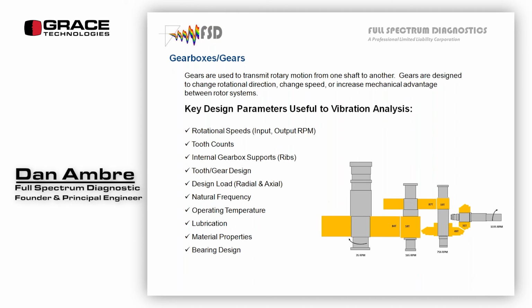But pretty quickly we found out, hey, we're not getting good trends. It's really high, really low, it's bouncing around all over the place. We decided to go in and make 6 routes, and each route would be a different product that they'd be putting through the extrusion process and through the gearbox loads. So now we had 6 trends, and they were all very good. Took a little longer to produce that many, taking data once a month, but they were all really good trends, and it was a great idea to do it that way.